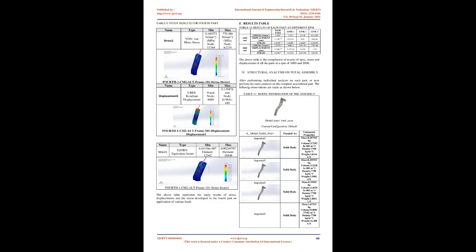Each node is fully described by a variety of parameters depending on the analysis type and the element used. For example, the temperature of a node completely describes its response in a thermal analysis. For structural analyses, the response of a node is described, generally, by 3 translations and 3 rotations. These are called degrees of freedom, DOFs. Analysis using FEM is named finite element analysis, FEA.